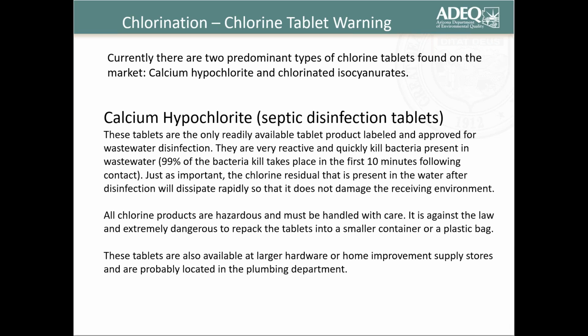All chlorine products are hazardous and must be handled with care. It's against the law and extremely dangerous to repack the tablets into a smaller container or plastic bag. These tablets are also readily available at larger hardware or home improvement supply stores and are probably located in the plumbing department. I did some online searches and I found them. So it's not like they're not available. And just keep in mind that when you have calcium hypochlorite sealed up in a tight container and you pop that lid off and get a whiff of gas, you're getting a whiff of chlorine gas there. Be careful.